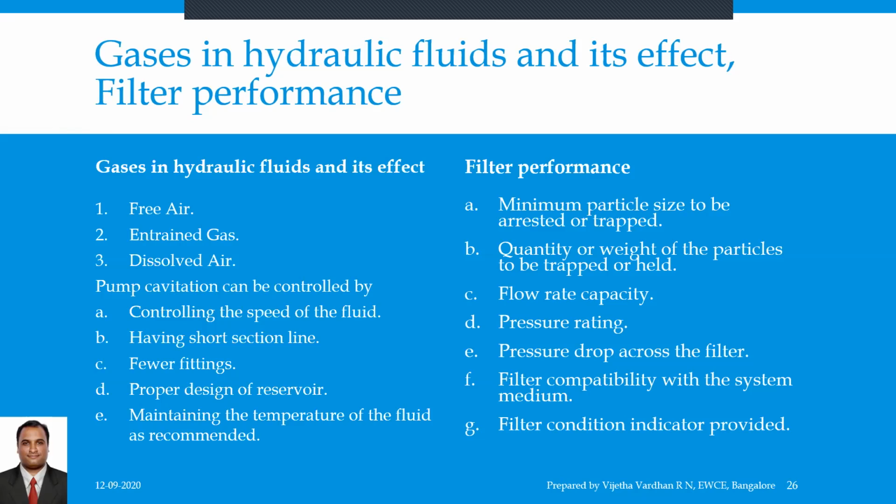A filter is a device which retains or traps insoluble contaminants from the fluid using a porous medium, and a strainer is a coarse filter. And the filter efficiency is determined as per the ISO standard 16889 multi-pass test procedure.